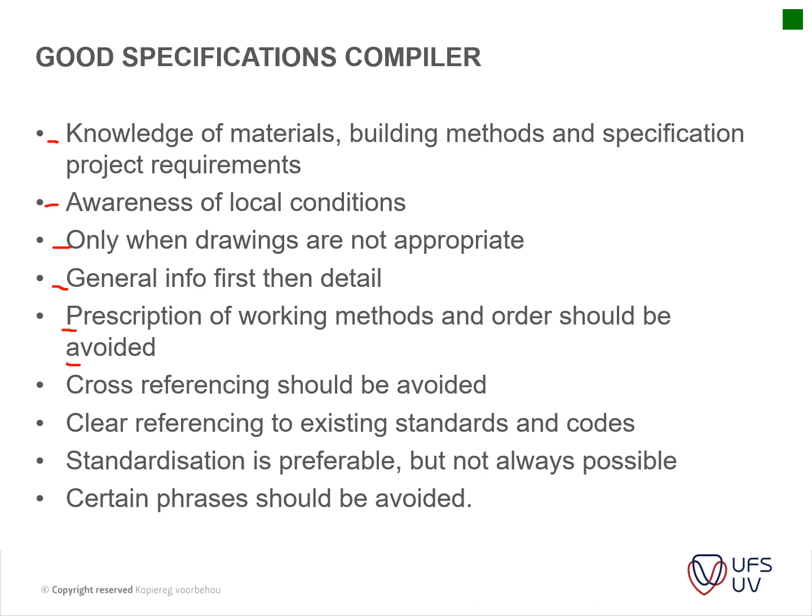Cross-referencing should be avoided, and especially in our computer age, it's something that crops up quite often. Whenever you're duplicating certain sections in a drawing, it pops up quite a lot, where you maybe forget a construction line, or the lines may have a different font setting, etc. Especially if you're working from old drawings to new drawings and the line settings aren't exactly the same. I've encountered that quite a bit.